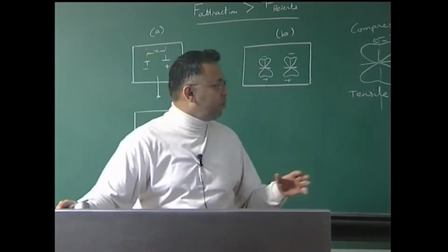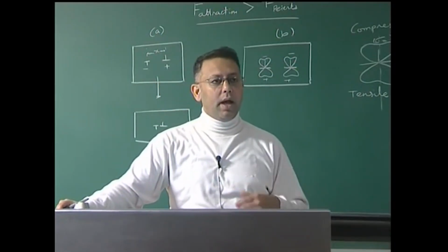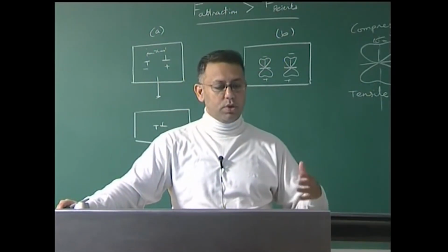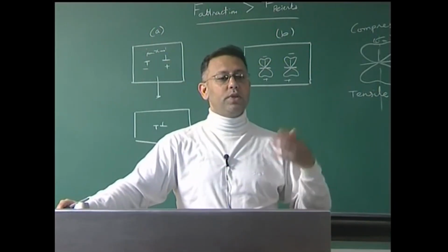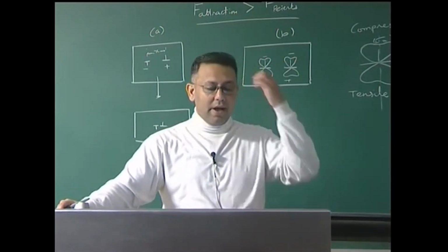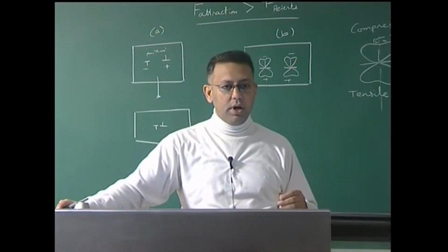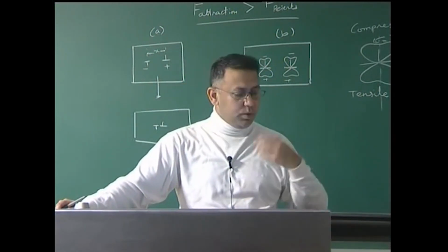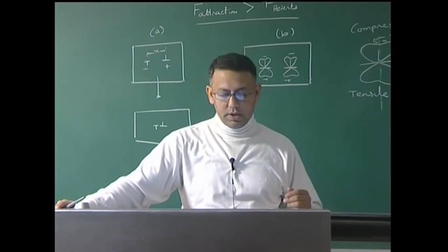And finally, I have to talk not only about these one or two dislocations, but the entire gamut of dislocations, and many of these dislocations will be lying on multiple slip planes. They could have defects within these dislocations which we will consider briefly later. In other words, I have a very complicated structure which is evolving under the external constraint, and I have to track how this evolution of structure gives rise to what we might call the properties of the material.